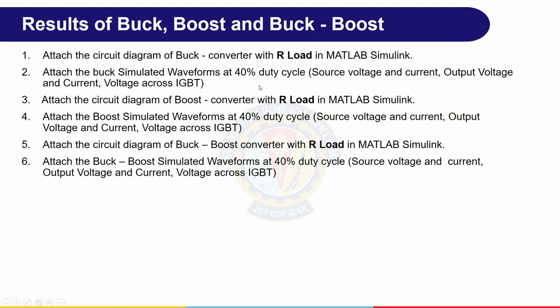Now with the saved files, attach the circuit diagram of buck boost converter with R load in MATLAB Simulink. Attach the buck simulated waveform at 40% duty cycle, source voltage and current, output voltage, output current and voltage across the IGBT also.